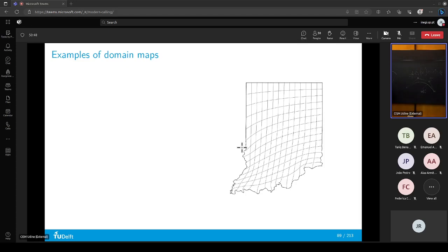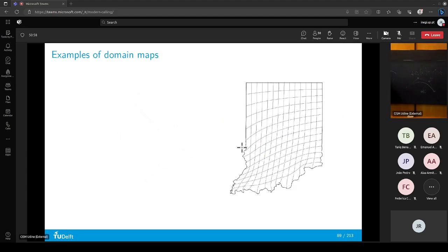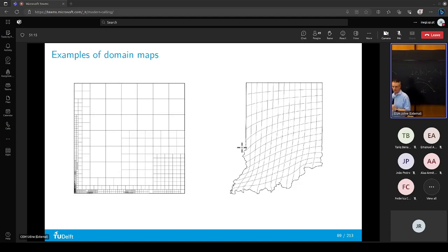What would your first association with that be? Is such a tensor product parametrization the best choice possible? Or if you would just take this and create a standard finite element mesh, would you go with a constant mesh size everywhere? Most probably not. So we need something adaptive, and there is something adaptive called THB splines, truncated hierarchical B-splines.